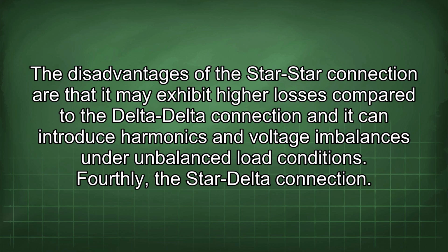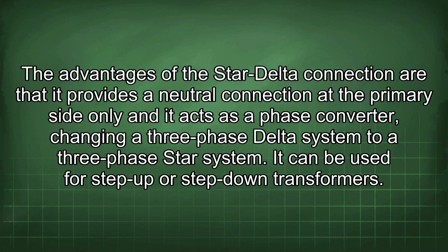Fourthly, the star-delta connection. The advantages of the star-delta connection are that it provides a neutral connection at the primary side only, and it acts as a phase converter, changing a three-phase delta system to a three-phase star system. It can be used for step-up or step-down transformers.